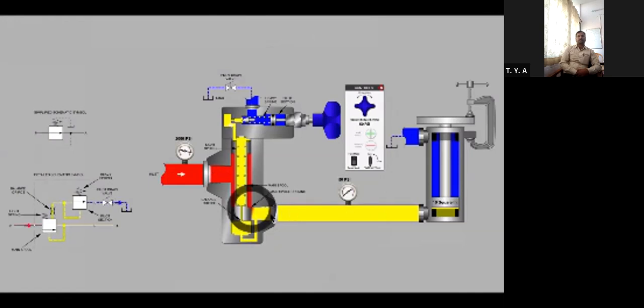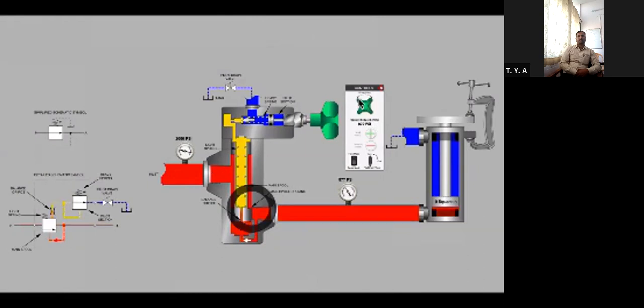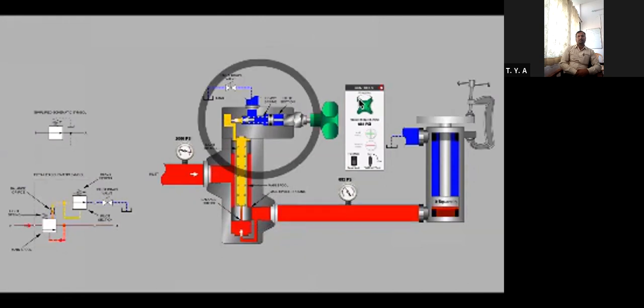Observe here at the main spool opening. If we quickly increase the pressure setting of the valve, the spool is opened for a longer period of time in order to bring more of the inlet pressure through to the outlet. In future videos, we will look at the function of the pilot section and also how to troubleshoot pressure-reducing valve problems.